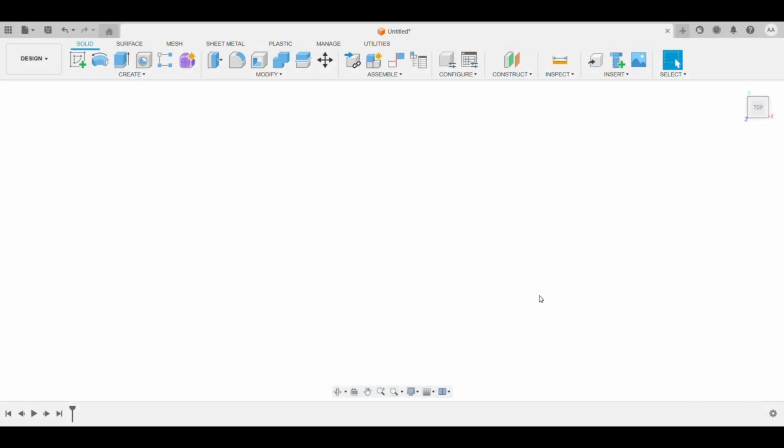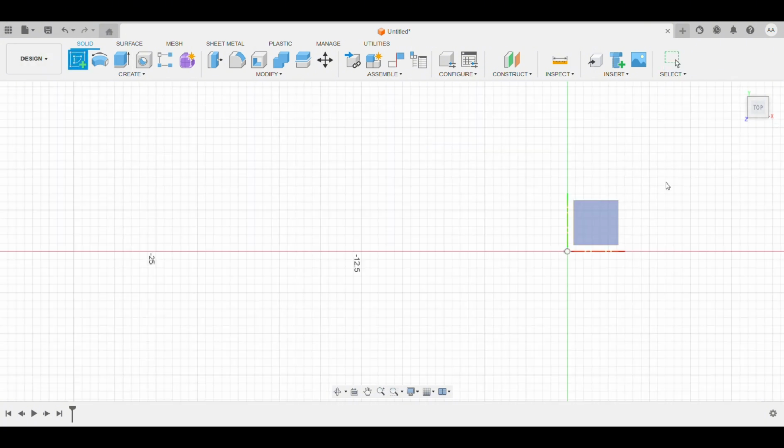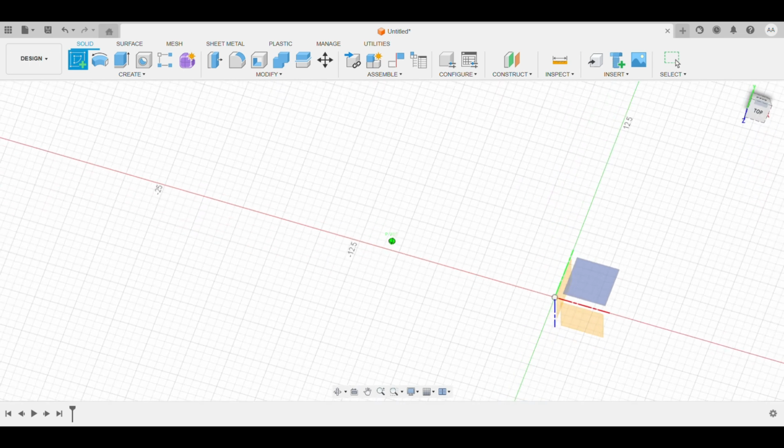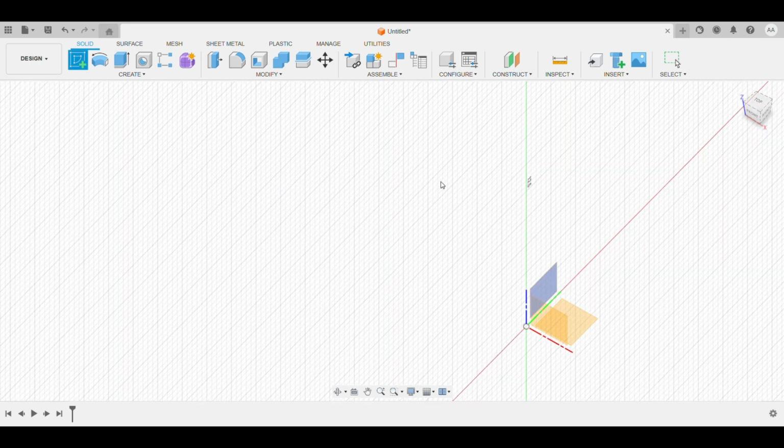All right, now Fusion 360 is software that's primarily driven by 2D sketches, and those are extruded or basically made into 3D shapes. So as you can see here, there's no shapes to choose from. These are all just features. So really what we need to do is start with a sketch. So I'm going to click Create Sketch, and then I've got these sketch planes to choose from. It really doesn't matter.